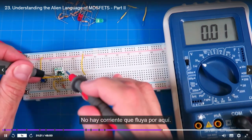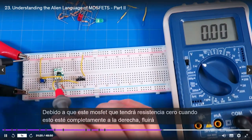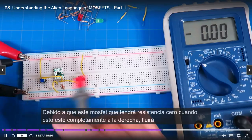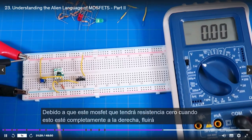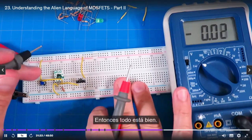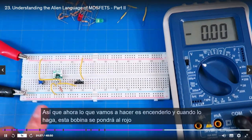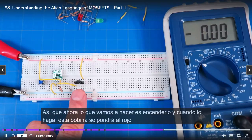There's no current flowing through here. When this thing is on, that drain to source will go to 0, because this MOSFET is going to have 0 resistance when it's fully on. It's going to be flowing a ton of current. Everything's good. So now I'm going to actually turn this thing on, and when I do, this coil is going to get red hot.